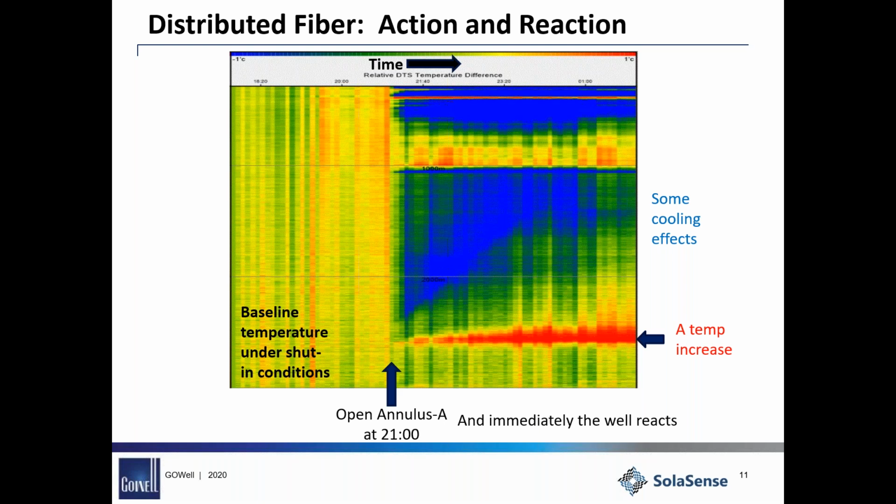We're much more interested in the backscatter throughout the length of the fiber. That's how the measurement is made. So fibers with more cells or more points for refraction and reflections to occur actually increase the SNR and sensitivity, especially for these microseismic applications.